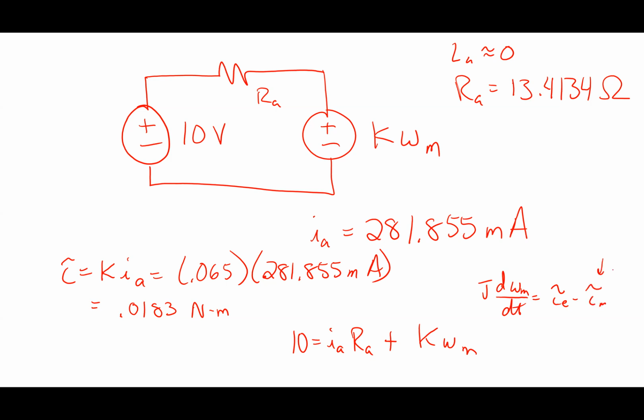If I grab the shaft, torque electrical is going to go up, right? And the speed is going to adjust itself so that the torque produced is going to exactly balance the torque that's needed to spin the load, right? So the thing's going to slow down and the torque is going to go up. All right, we're going to look at that more carefully on Wednesday. We'll look at that in some more detail. But this is the basic premise.